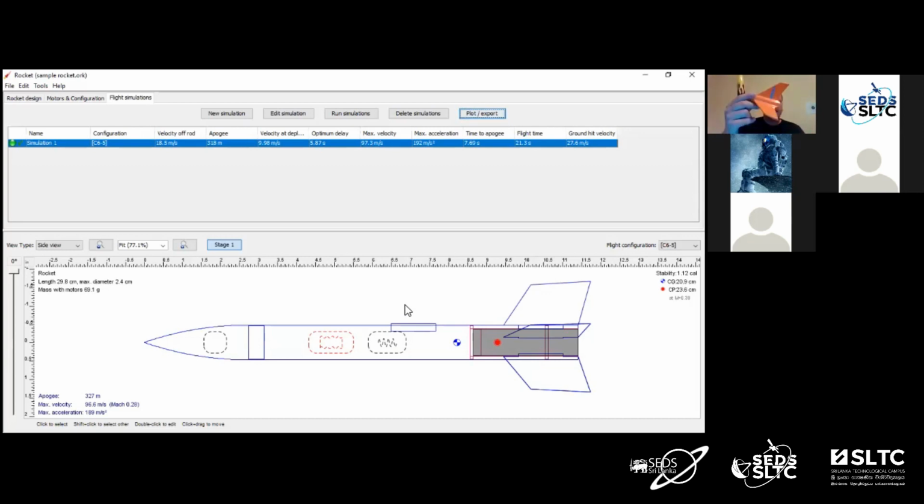So we could have our booster motor in this rocket, keeping in mind that for a booster motor, where we had the C6-5 with the 5-second ejection delay, it would be a C6-0. There's no ejection charge. It's just going to burn the propellant up, and then it will burn right up into the next sustainer motor above it. So this would be a C6-0 if it was a booster. Again, that just slides in here.